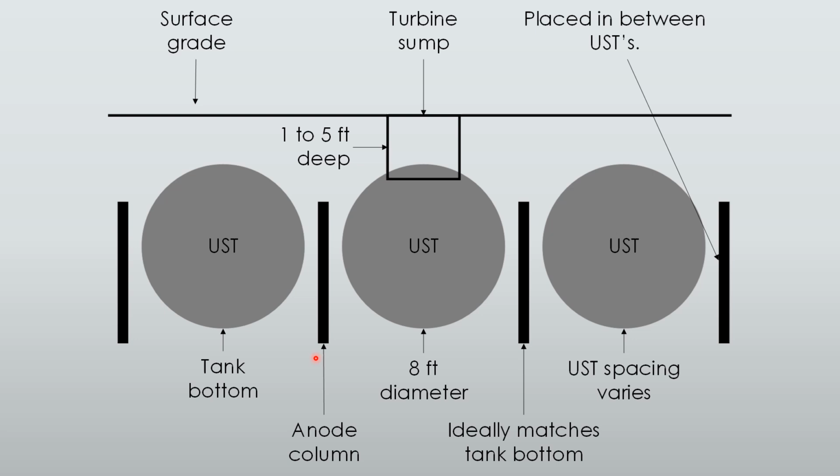These are our anodes. We want them well distributed. We want them in between the tanks so that the current can travel along the portion of our tank body and polarize as much of the surface as we can. I have seen proposed systems, we'll get to another top-down view of the tanks eventually, where there's a different proposed method, but these are what I see most common in industry, and this is what you'll see if you're out in the field.